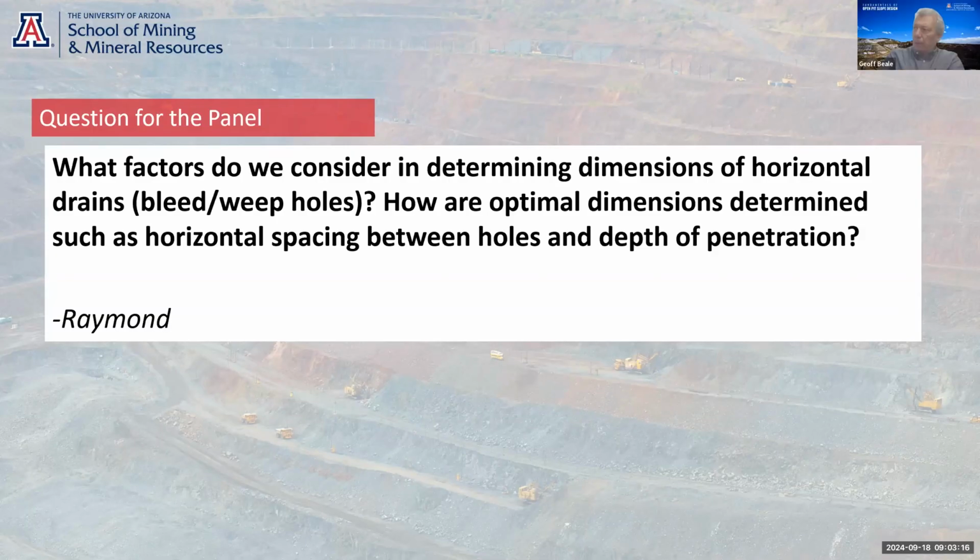And there's a great example I'm just working on now where we've got piezometers about 10 meters behind the slope. And every time they get a rainfall event, those piezometers rise by about 15 to 20 meters. So now we've put in a whole pile of, I think, 15 to 20 meter long drains. And every time now we get a rainfall event, the water comes out of those shallow drains and the piezometers only rise by about a meter. So the weep holes are a good concept just to relieve transient pressures shallow in the slope.